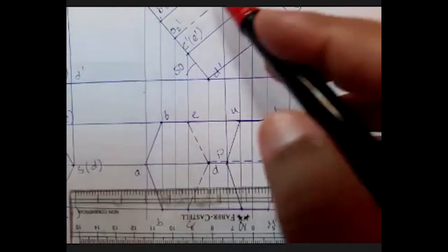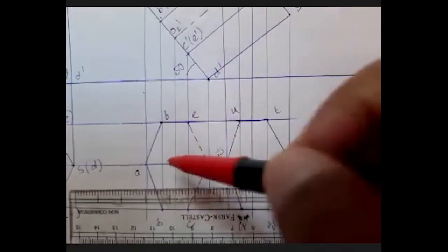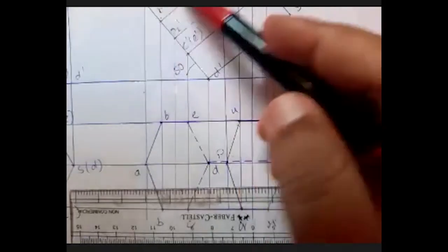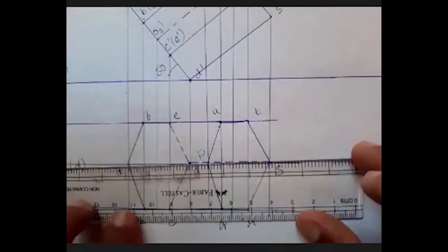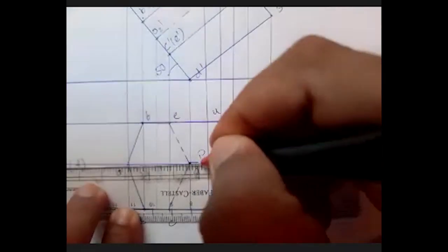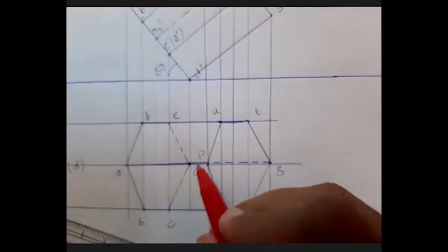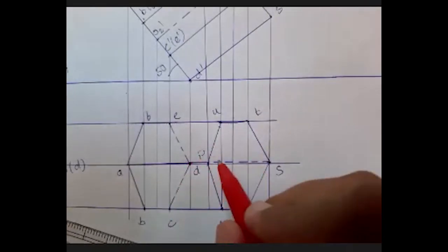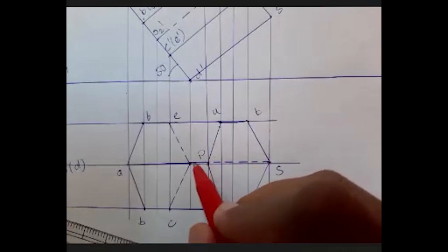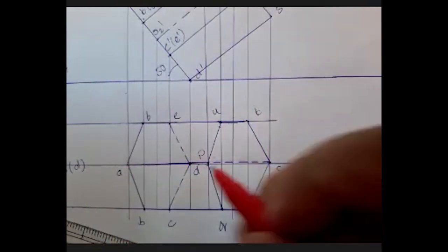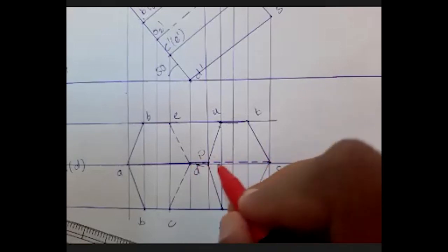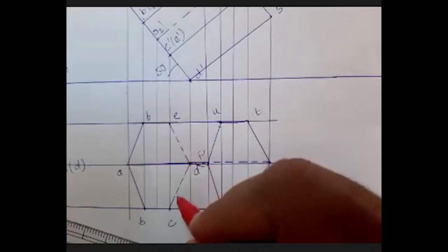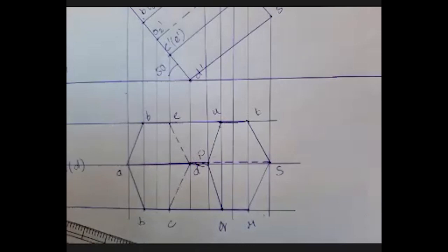And then I have A to P. A to P is a line which is the longer edge here. A to P is this line which will never be dotted. So I'm going to join A to P. So I have two small lines and one large which is dotted. But this line will be merging with A to P, where I don't get dotted in this portion only. In the other line here I get dotted, as well as this is dotted. Dotted means nothing but it is my hidden line.